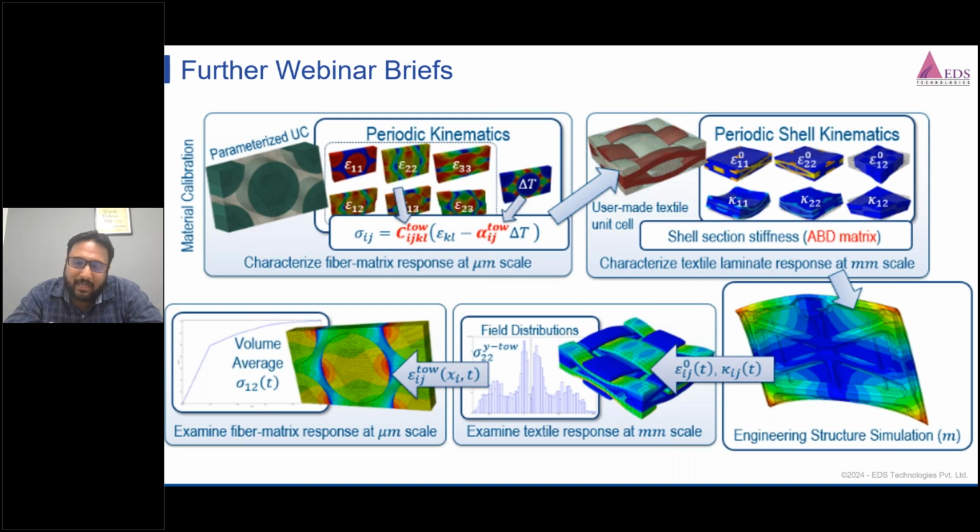What we can do is input the two-dimensional properties, along with the density and fiber volume fraction. Based on the Mori-Tanaka equations, it will automatically calculate the ABD matrix and give you the three-dimensional properties of a fiber based on the volume fraction as well as densities.